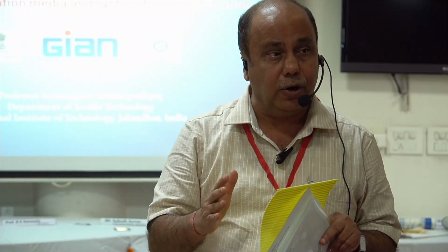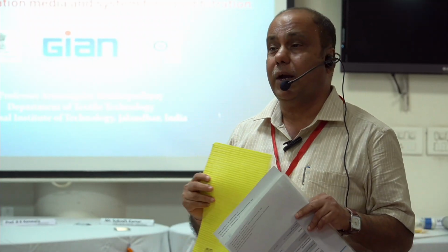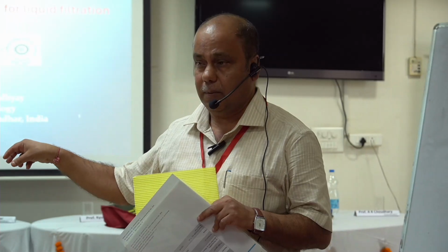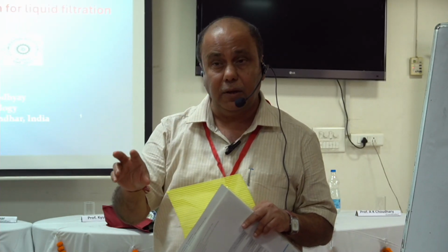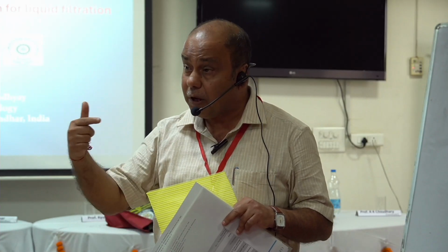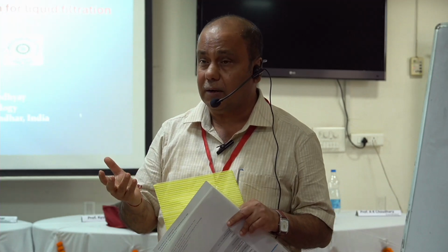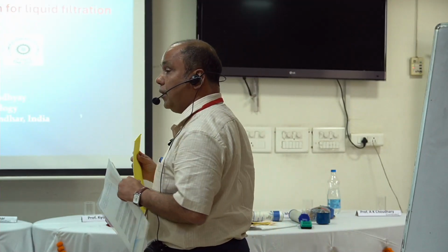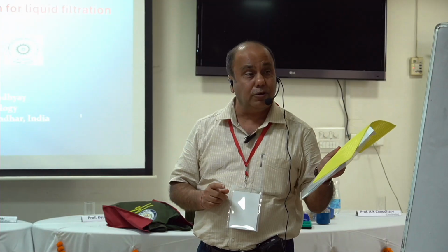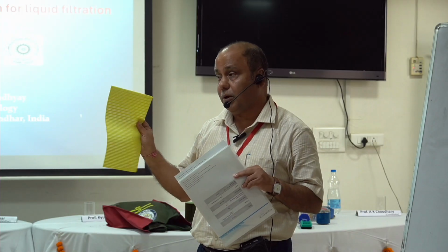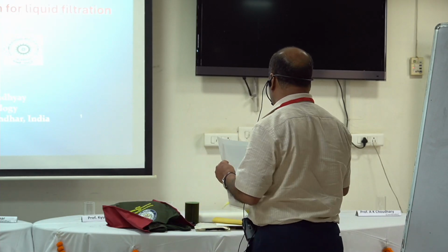So we will have to make a balance between the flow, because flow should not be restricted, and at the same time we want the particles to be arrested. So the challenge could be very different depending on the case. Challenges are not the same, because it all depends on the contaminant concentration, size of the contaminants, volume of the contaminants, shape of the contaminants. So a lot of things matter whenever trying to develop the media. Sometimes the abrasion property may become an important property, because abrasion damage can also happen during liquid filtration. So we will have to choose a proper filter media whenever we are going for a certain kind of application.